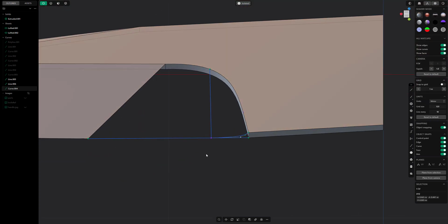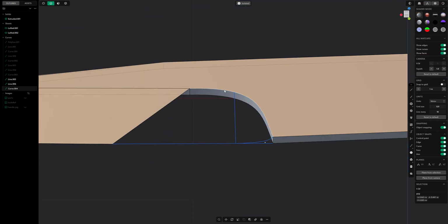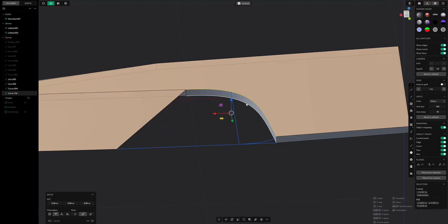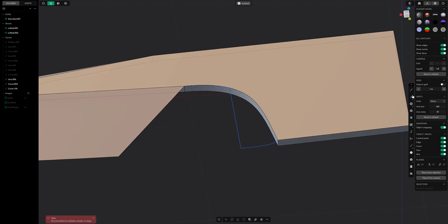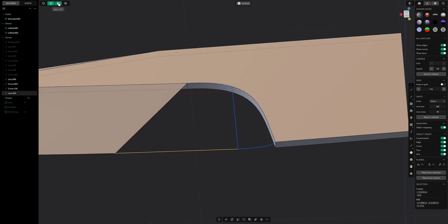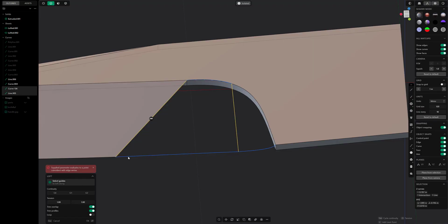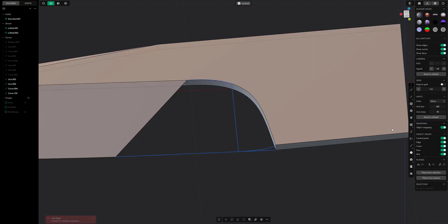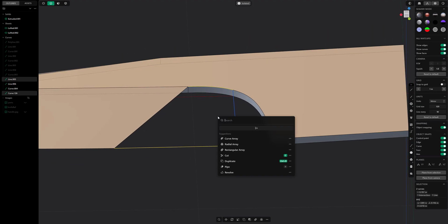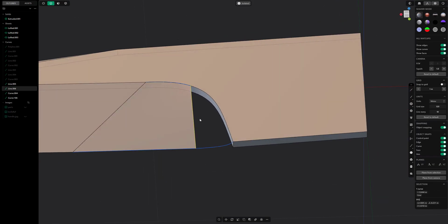So now I should be able to loft the smaller section with a G0 and a G1, and the section to the right with a common loft. Here I need to make sure I have segmented edges, so I can either delete and then create them, or I could split an edge. So here I just trim that edge and loft again, and then select the adjacent edges. To get this corner, I just want the one spot.